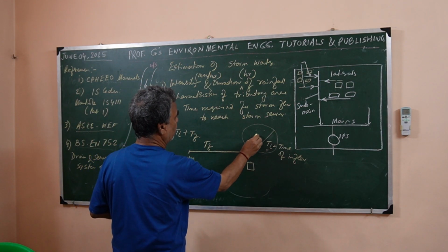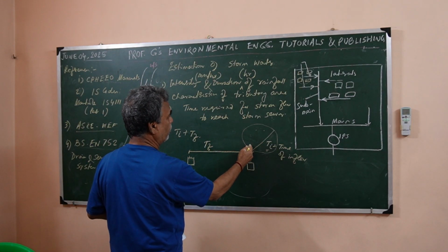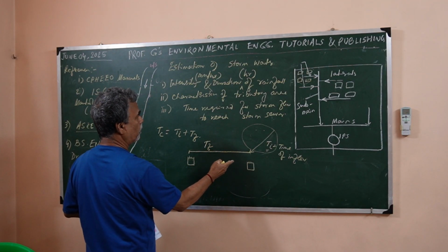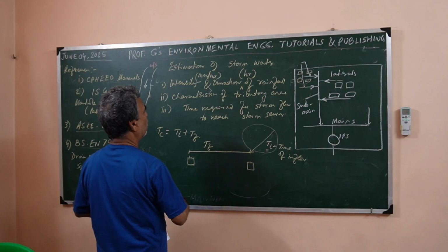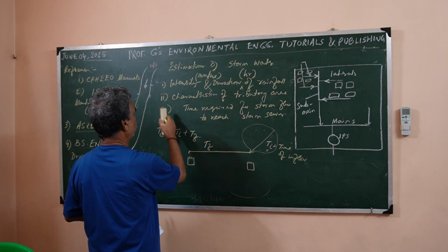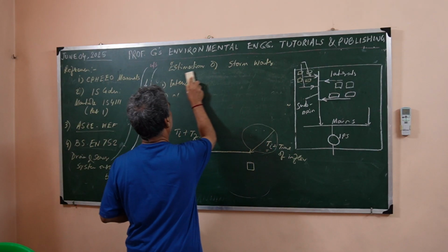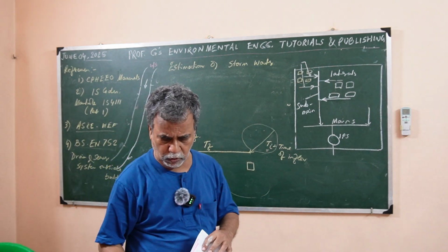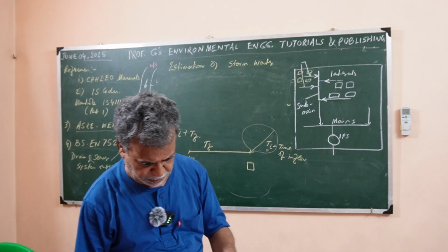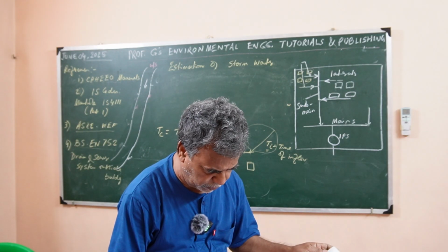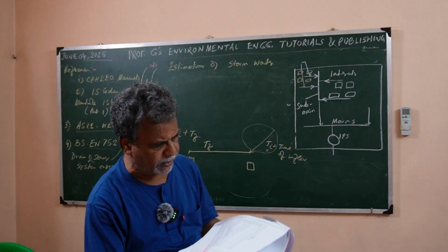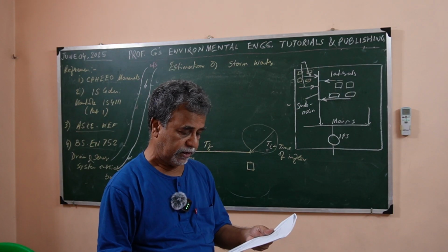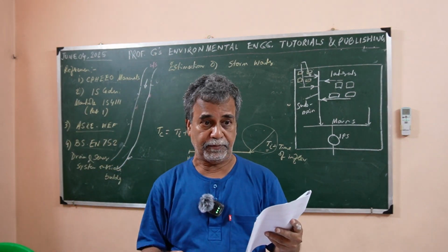That means the soil characteristic, the topography, vegetation and other factors will decide the ultimate effective perviousness, and the intensity and duration of rainfall will also matter. The runoff coefficient you will get for different types or shapes of area, and that would be in the manual. I will discuss this later when we talk about the design in more detail.